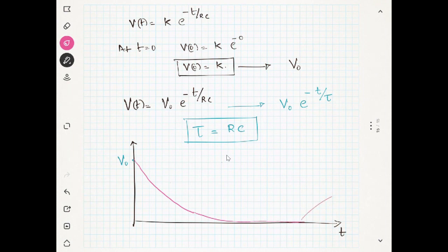At this point, you will say this is t equal to 5 times the time constant. I told you it is less than 1% of V0. The value is very, very small. If V0 is 100 volts, at this point V of t may be less than 1, about 0.6 volt.